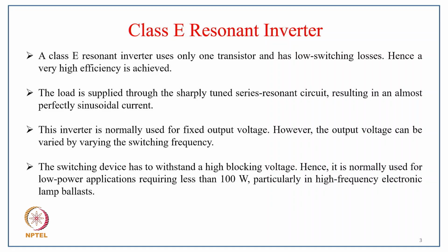The load is supplied through a sharply tuned series resonant circuit, resulting in an almost perfectly sinusoidal current, and this inverter is normally used for fixed output voltage. However, the output voltage can be varied by varying the switching frequency, and the switching device has to withstand high blocking voltage. Hence, it is normally used for low power applications requiring less than 100 watts, particularly in high frequency